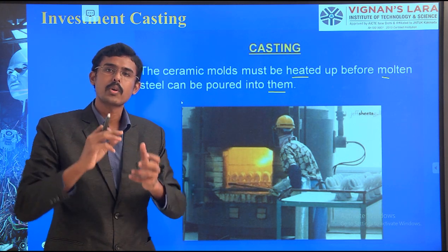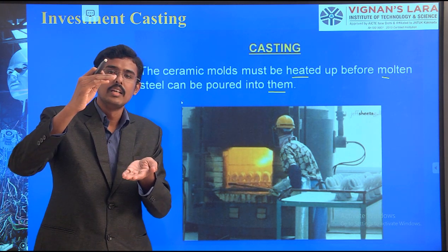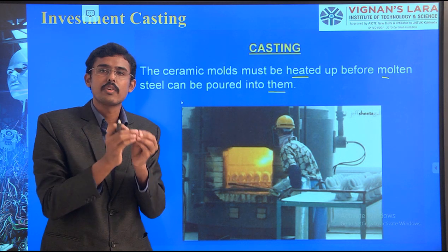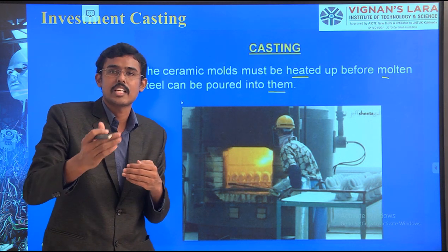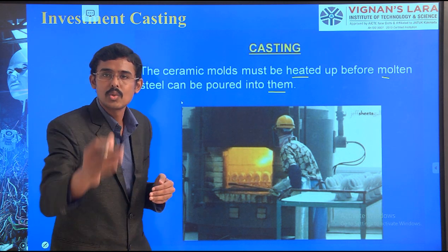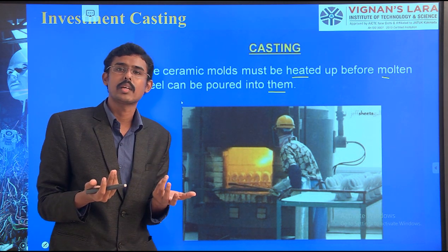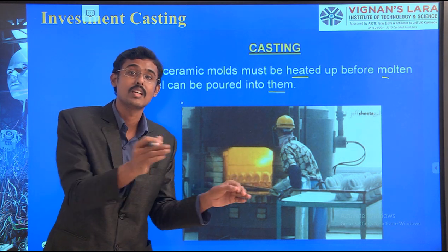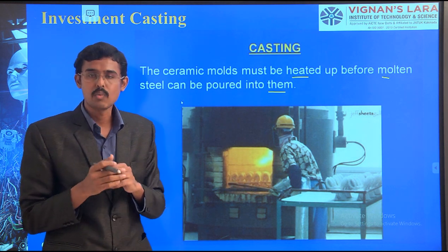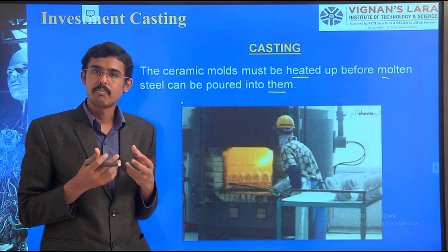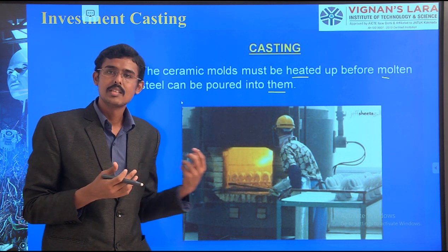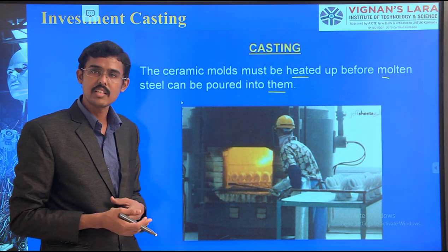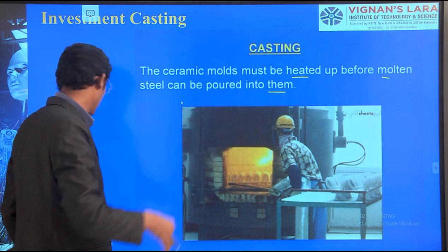Rapid, progressive solidification will happen. Therefore, to reduce the progressive solidification, we are keeping the ceramic shell warm in such a way that both solidify slowly. Always the temperature exchange takes place quickly from the molten metal to the ceramic shell. In such a way solidification happens quickly. Therefore, cracks are possible, and progressive solidification may happen. Therefore, the metal may not reach all the complex design corners, which we should avoid. So I am pre-warming the ceramic shell mold. That's why I keep this shell cavity in the oven furnace, heat it just to warm it, and then we have to pour.